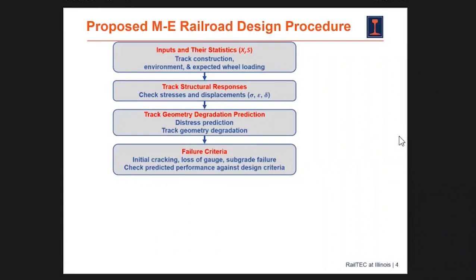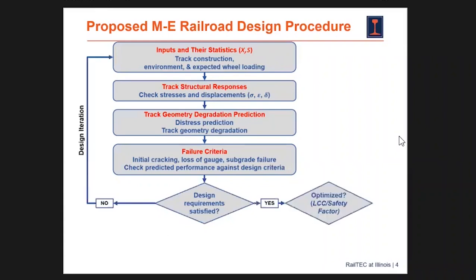Each railroad can have their own thresholds. And in general, you would probably say, I'd rather fail up high in my fastening system than down low in my subgrade, where it's going to be a pain to actually go out and fix. So you can set your failure criteria appropriately. Then go back and ask, did we come up with the right initial conditions? If no, try again.